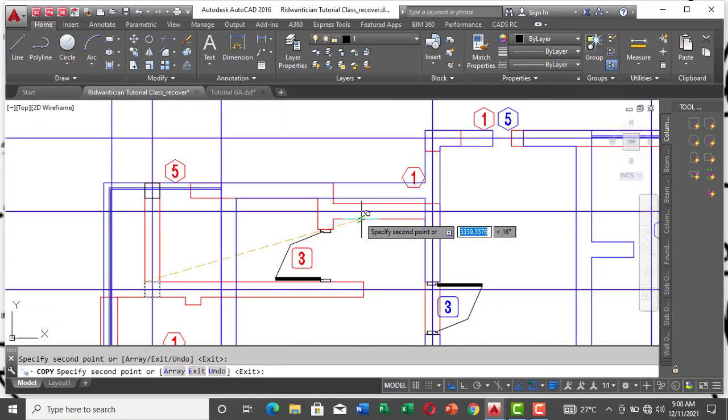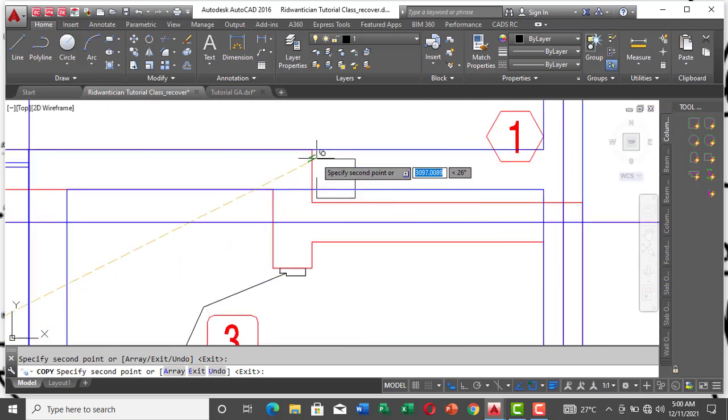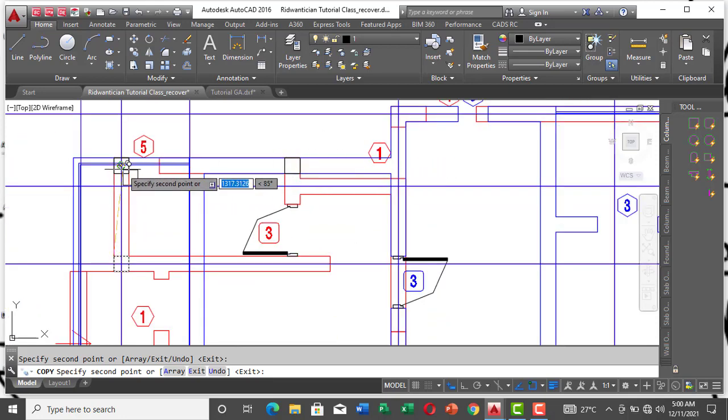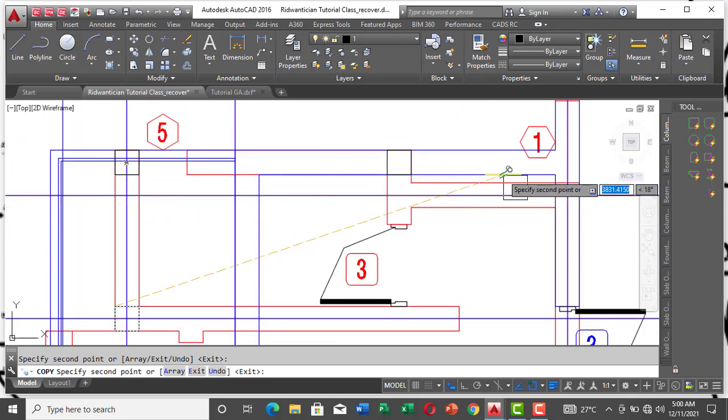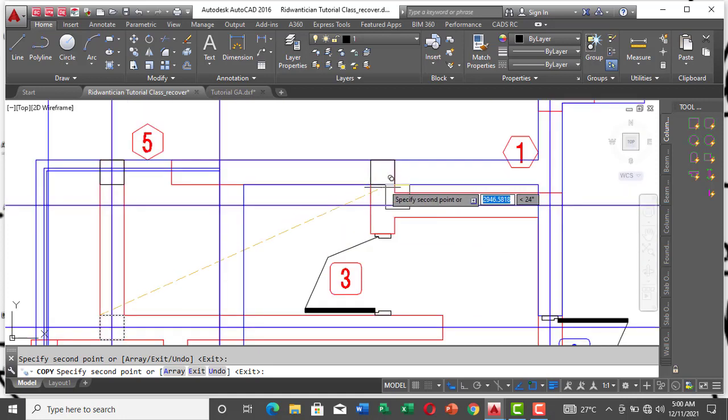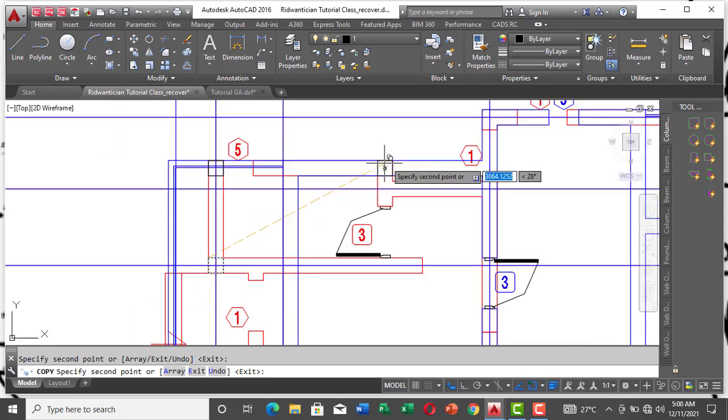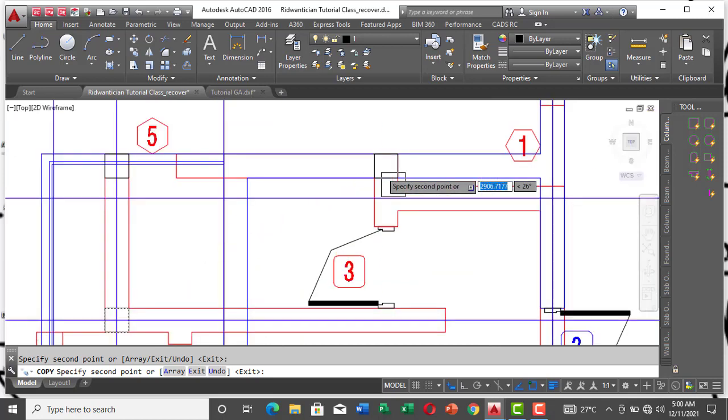Then let's come to this edge. This is the other corner, so we need one here. Now let me trace it from here. You need one here. This is the corner of the ground floor. This is the last corner here. So you need a column here, and that column too can go up to the first floor. You can see that you still have blue line crossing too. So you have both blue line and green line crossing. It's only this that will terminate at the ground floor. This will go up to the first floor. This will not terminate at the ground floor.